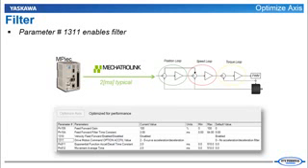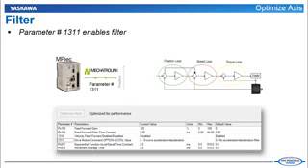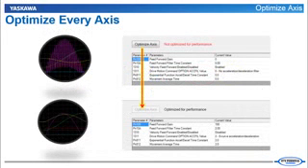Even without controller feed forward, the controller position command is still received at the mechatronic cycle. A servo motor tuned for high performance can respond very quickly, producing torque ripple at this rate. The command can be smoothed out using a filter selected by parameter 1311. This distributes the position command over the mechatronic cycle. The servo pack internal position loop receives the filtered position command, resulting again in smooth motion with low torque ripple and reduced motor heating.